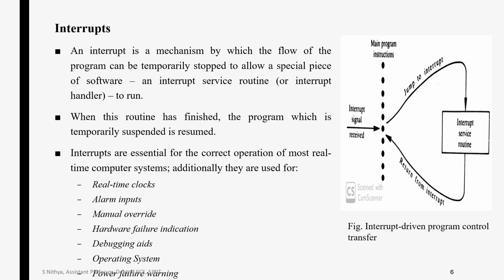So the next concept which is used here is interrupt. An interrupt is nothing but a mechanism by which the flow of a program can be temporarily stopped to allow a special piece of software, an interrupt service routine, or interrupt handler, to run.